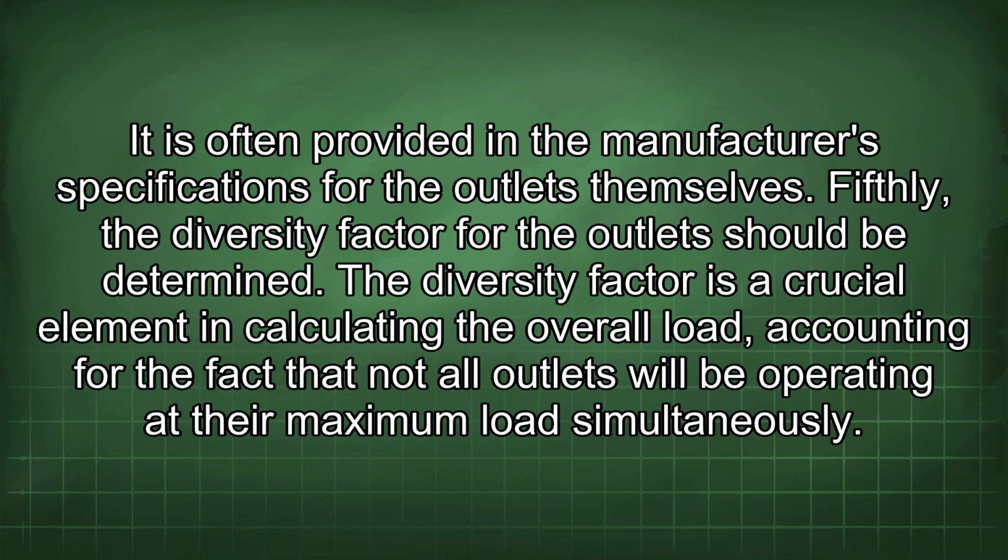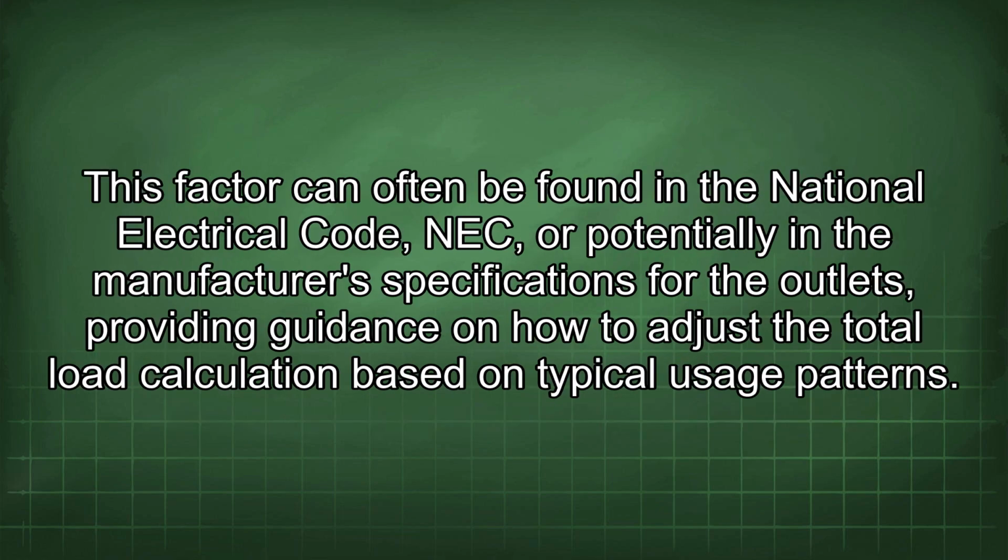Fifthly, the diversity factor for the outlet should be determined. The diversity factor is a crucial element in calculating the overall load, accounting for the fact that not all outlets will be operating at their maximum load simultaneously. This factor can often be found in the National Electrical Code, NEC, or potentially in the manufacturer's specifications for the outlets, providing guidance on how to adjust the total load calculation based on typical usage patterns.